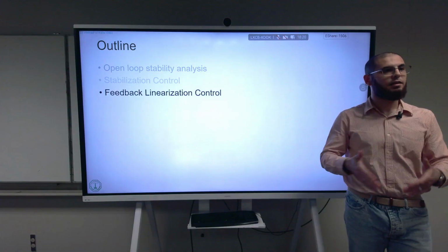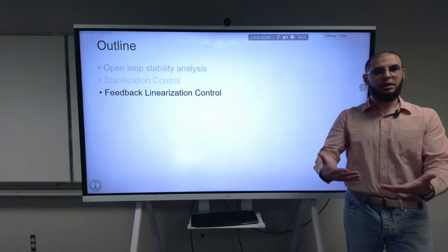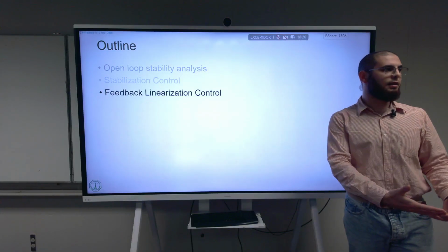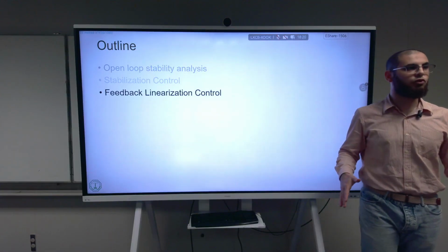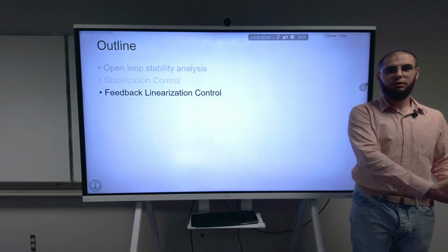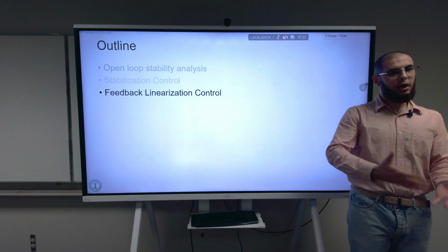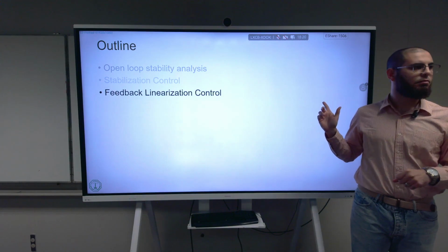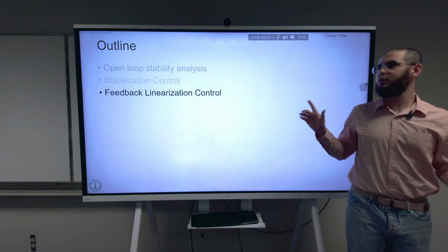The whole idea is that I have a nonlinear system with nonlinearities. What do I do with it with the controller? Kill the nonlinear terms. Full stop. You have control. I did modeling. I know what the nonlinear terms are. Why don't I cancel them? Did we do something like this now? We did the gravity compensation. That's exactly what we did in the gravity compensation, right?